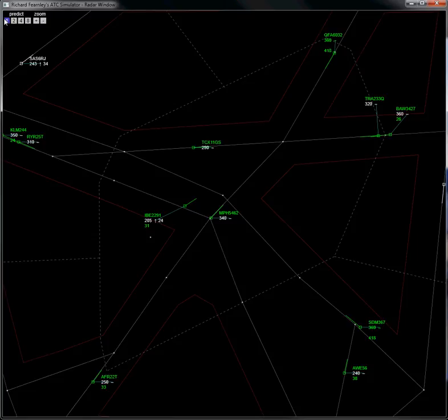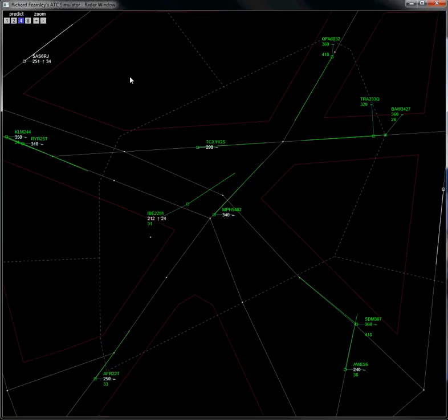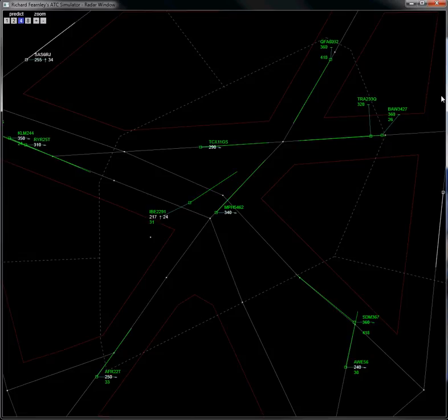Moving back towards the exercise, the third aircraft at flight level 360 is this Speedbird 3427, which I'll assume by right clicking, also the Transavia front. This is a much more pressing conflict, as it appears they're going to collide in 4 minutes or so. I will solve this particular conflict by a vertical solution, since the Speedbird 3427 we see here has a planned flight level of 260, so he's descending.